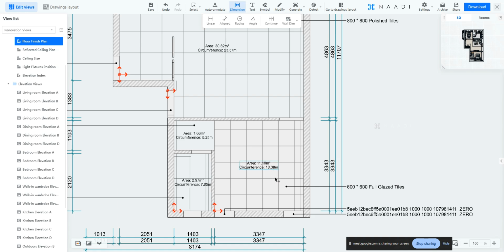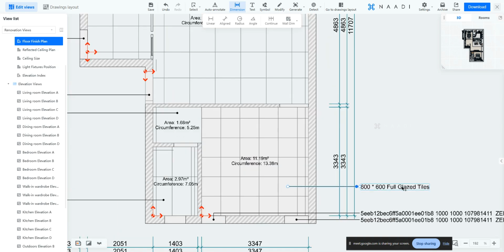But some details might miss. For say, the tile was not annotated here. The starting point was not defined for this, right? In those cases, I clicked on this auto annotate option. This auto annotate option, shortcut is Shift A, is like a refresh tool. Okay, it will just refresh and check what are all the updates which are done in the model, and it will again update your 2D drawings based on the model changes. Okay, so on most cases it will be updated, but it's better that you just click on this auto annotate once and get the updates reflected in your 2Ds as well.